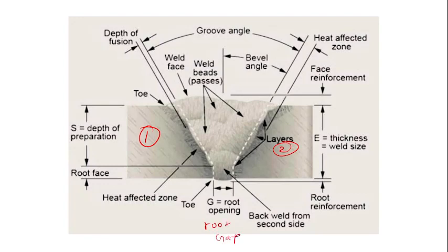This is the shortest distance. Why do we provide it? So that the penetration of the filler material will be high. That is why we provide a root gap or root opening.